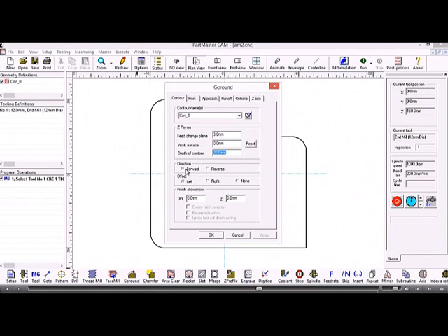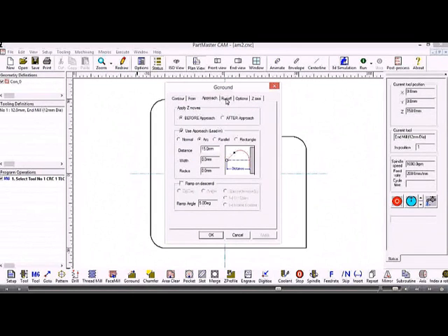The direction of cutting can be forward or reverse. If you remember in the previous video when we created the contour we had the start point as the bottom right hand corner and the cutting direction was to the left, so that's the forward direction. To cut the tool on the outside of that would be left of that line, but if we want to change our mind we could cut reverse, or we could offset to the right, or we'd have no offset at all so the tool sits on the line. If we want to leave finishing allowances, this is where we set them up. Other options include the approach and go round, which we'll leave the defaults as they are, and then we'll go into more depth about these parameters in subsequent videos.